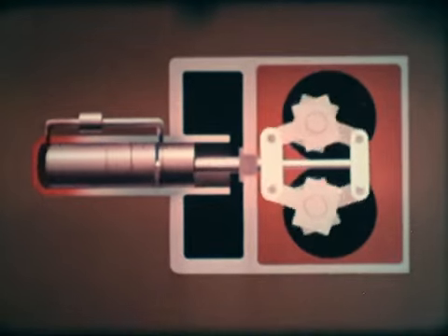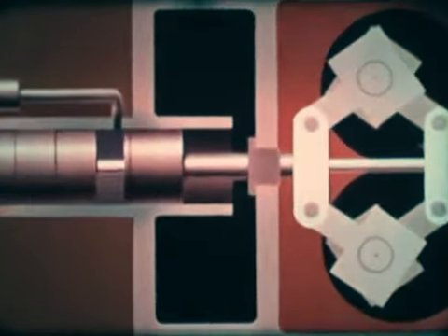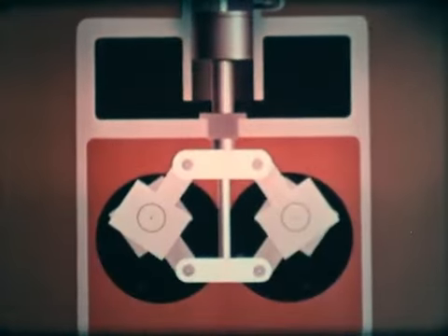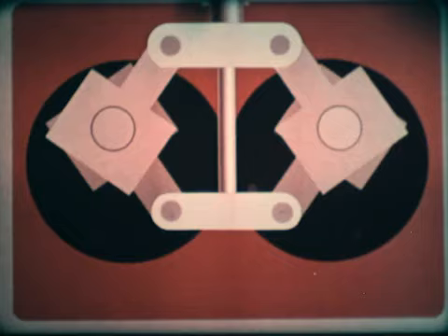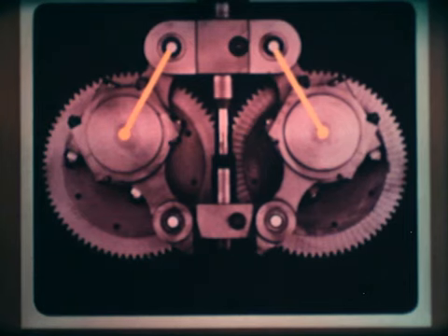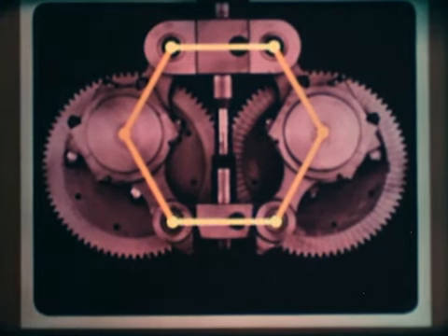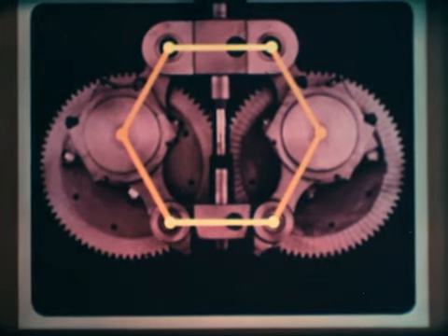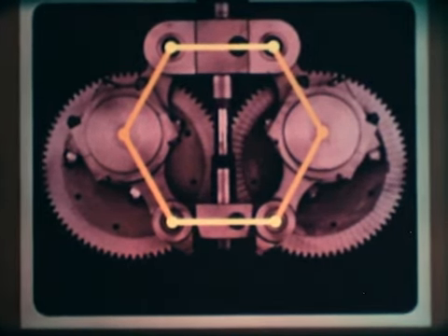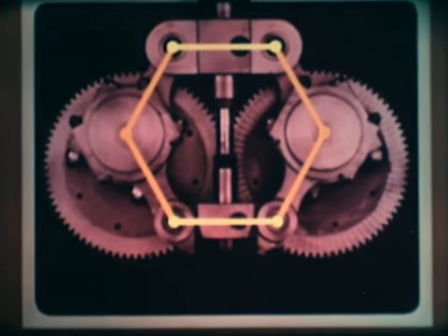This is how the rhombic drive is built up. The mechanism comprises two pairs of connecting rods of equal length. One pair connected to the yoke of the power piston, and the other pair to the yoke of the displacer piston. The yokes are also of equal length. Due to the symmetrical build-up of the drive, there are no resulting inertia forces in the horizontal direction. Furthermore, the vertical inertia forces acting in the mechanism will not be affected on the assumption that the masses of the pistons are concentrated in their respective yokes.